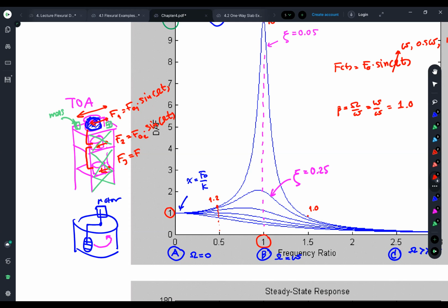Go clockwise and counterclockwise and put the initial position of the paddle, I mean the mixing machine, at 90 degrees or 180 degrees, for example, when you start the machine. That totally removes the vibration. Totally. Very, very smart idea. And thanks for sharing with us. Thank you.